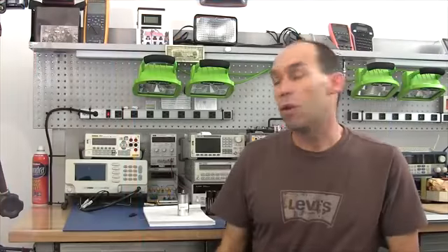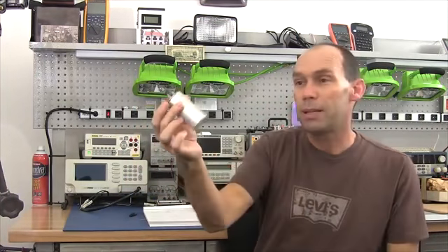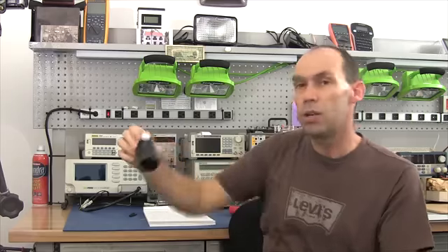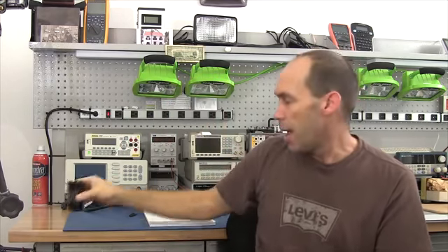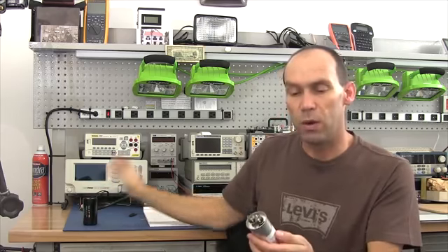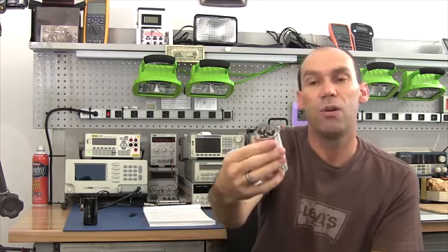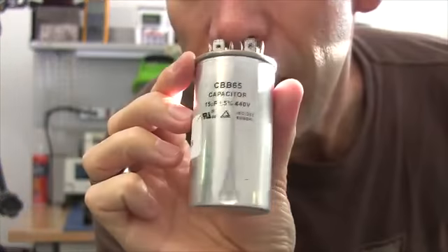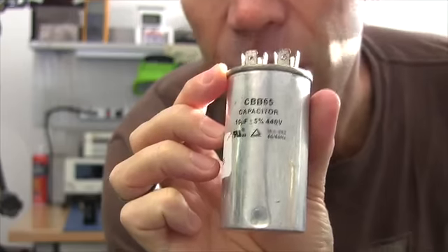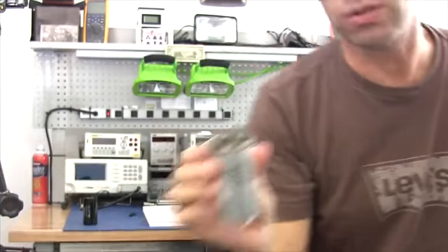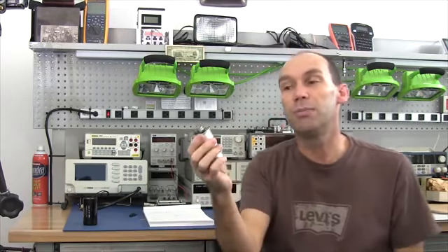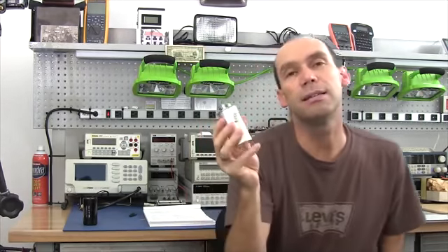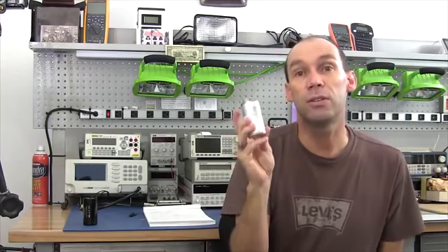Right, so before we end off, the one thing I want to highlight, going back to safety, is that I've got this one capacitor which is a motor starting capacitor, rated for 220 volts. I've got another one here which is rated for 440 volts. If you have a closer look, you can see on there it says 440 volts, and you certainly wouldn't want to touch that if it's sitting at that voltage. You really need to understand how to discharge these safely, so certainly do beware.